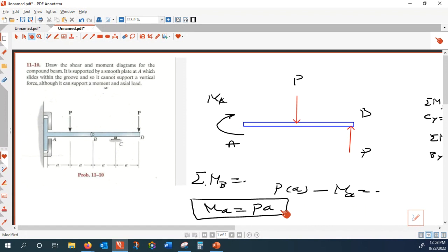Just AB. With AB, how many zones do you identify? Between A to the middle, the load doesn't change. Suddenly, you have a discontinuous shear, right? And between P and B, nothing changes. So the two zones is enough to describe AB, isn't it? Two forces.